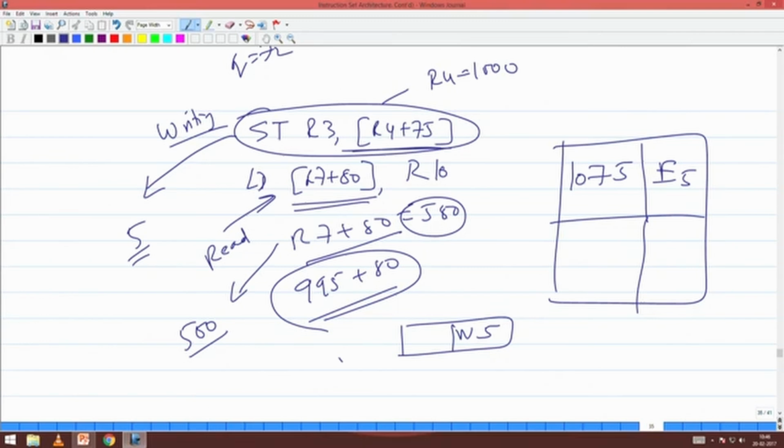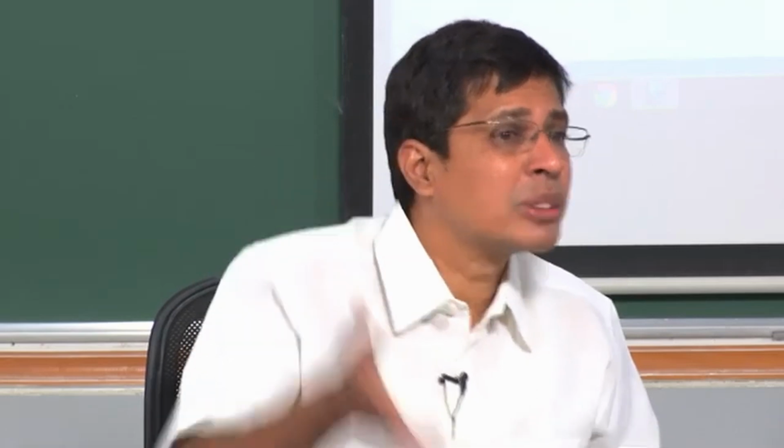Renaming happens with the unit number. Now before coming to your question, what should be the size of this content addressable memory? At the most, the number of loads that can happen is equal to the number of units. So there will be at most 4 load store units. So for the content addressable memory I just need 4 locations, right.